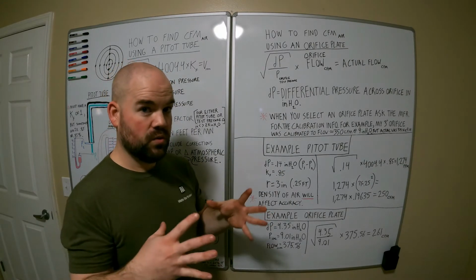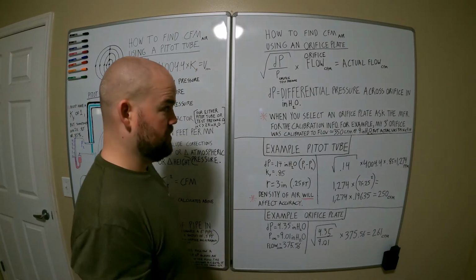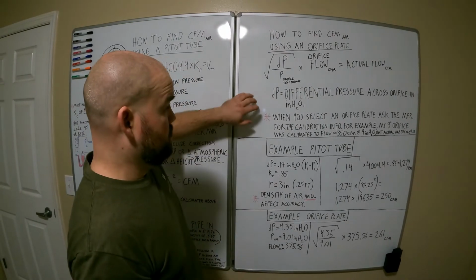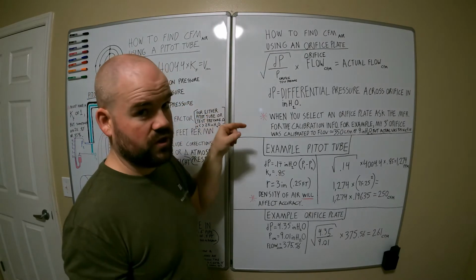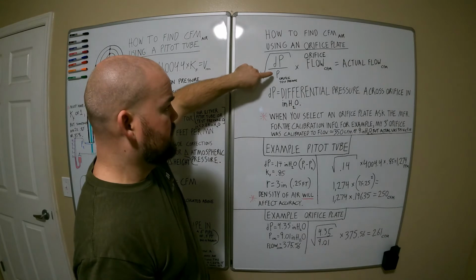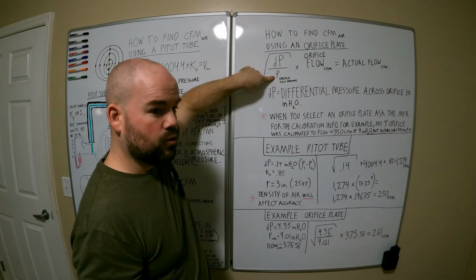You want to know plus or minus a couple CFMs, because it makes a big difference in an engine, especially when you multiply it by 8 cylinders. So you want to make sure you get as accurate as possible. This is where you're going to calibrate your bench, and I'll show how that works. But anyway, this is the test pressure that you're testing your orifice to.